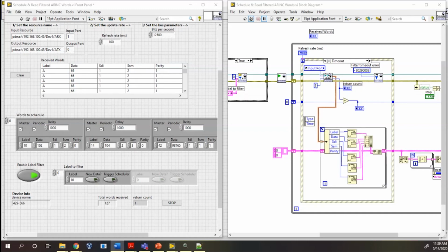And certainly that application could be LabVIEW, it could be Python, it could be just about any language in that case. How can I self-test an ARINC429 I/O board? One of the features we have is the loopback test that I discussed, in that we can run the board without anything connected and read on the same channel that we're using for output and input. Hopefully that makes sense. So channel 0 can be used for input and output. So you can send a message and receive it without anything connected.